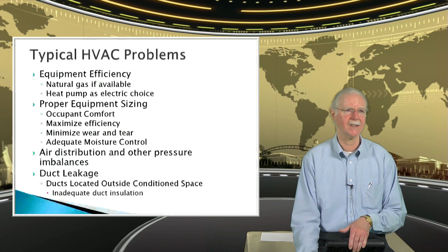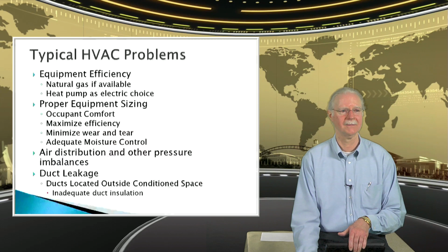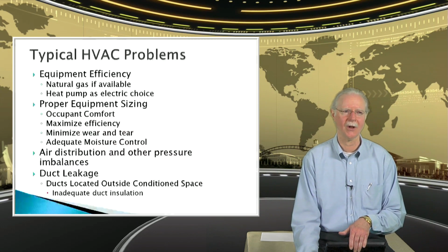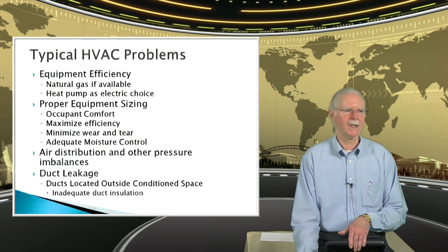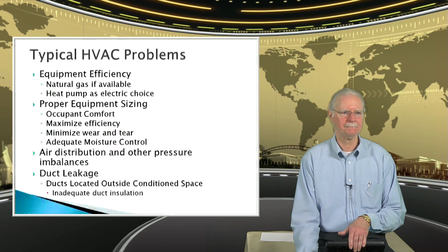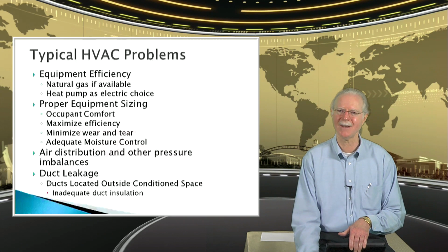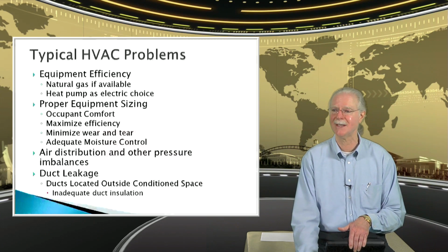When we're dealing with retrofits, we've got this whole idea of what's worn out. Does a piece of equipment that has 90% efficiency when it's installed have 90% efficiency 10 years later? The likelihood is next to zero. And then we've got this whole issue of moisture control. It's the reason why we call cooling systems air conditioners most of the time, because we're conditioning the air in more ways than just cool. We're also dealing with removal of particles and changing humidity levels.